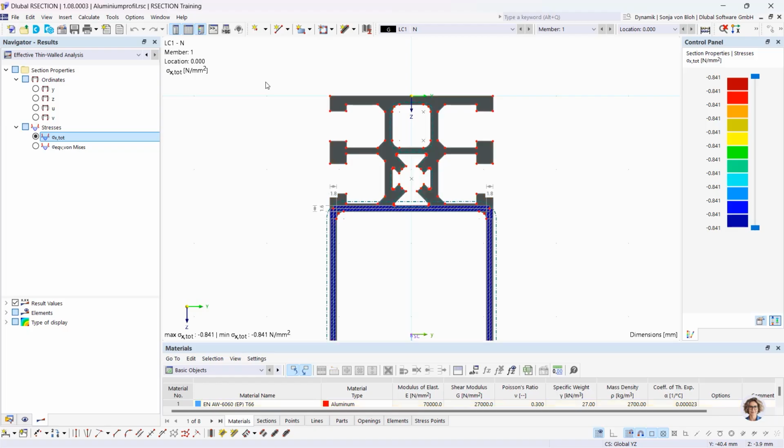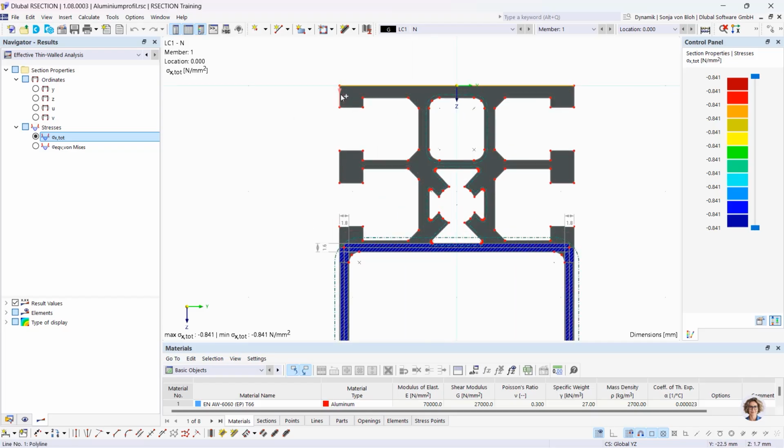You can also select individual objects. To do this, left-click on the objects that you want to select. If you want to add objects to the selection, hold down the Control key and then left-click on the corresponding objects. If you want to remove objects from the selection, then hold down the Shift key and click on the objects.